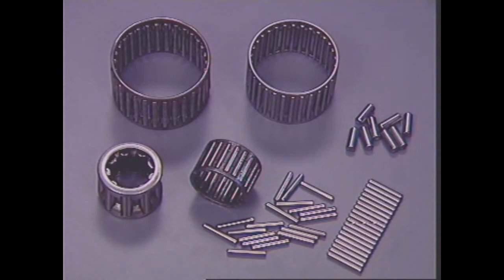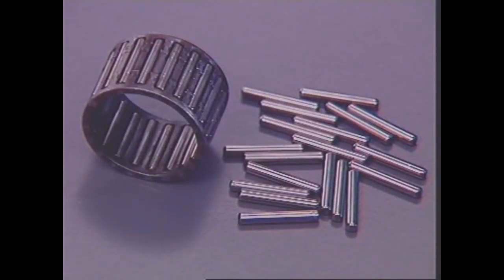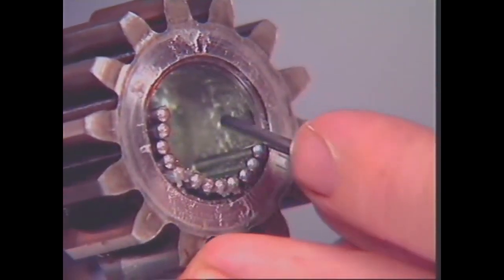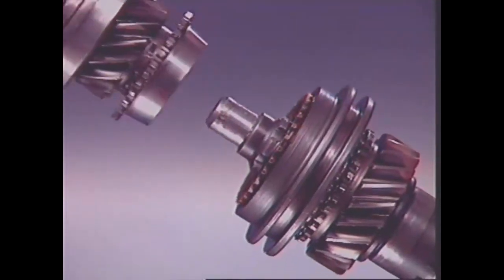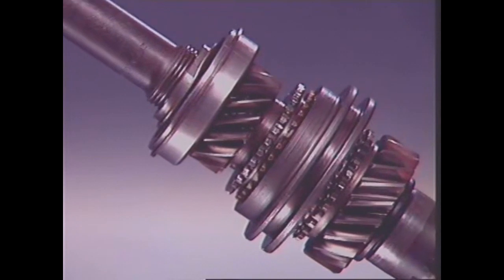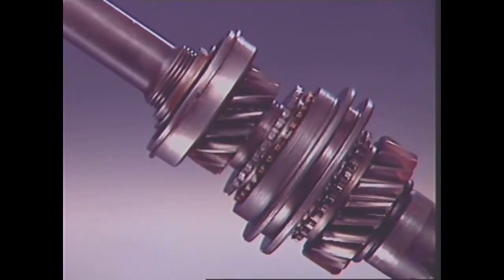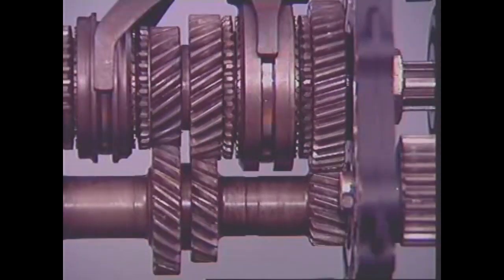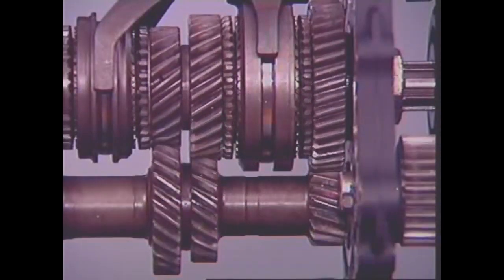Roller bearings are common where loads are purely radial. Needle roller bearings can be caged or as a loose number, assembled to operate directly on a hardened gear or shaft. Typical applications are the spigot on the front of the main shaft, supported in the rear of the input shaft, and in some cases on the counter shaft, and the freely rotating gears on the main shaft.